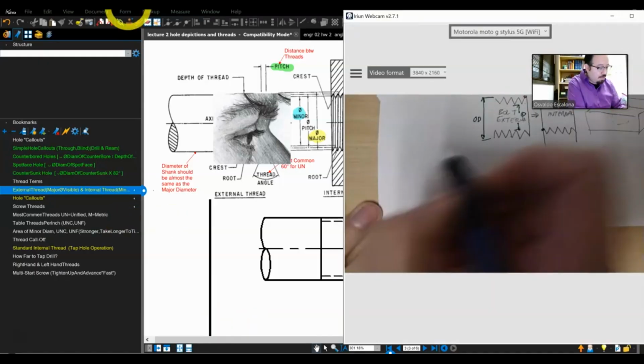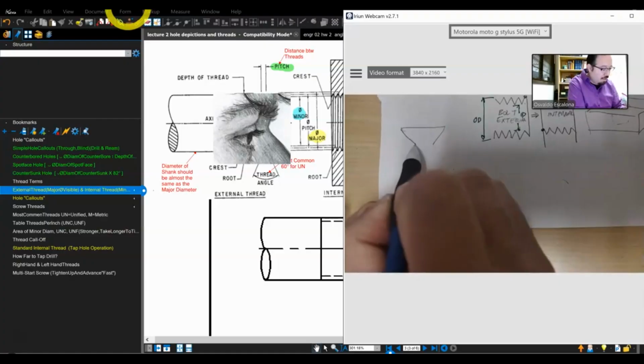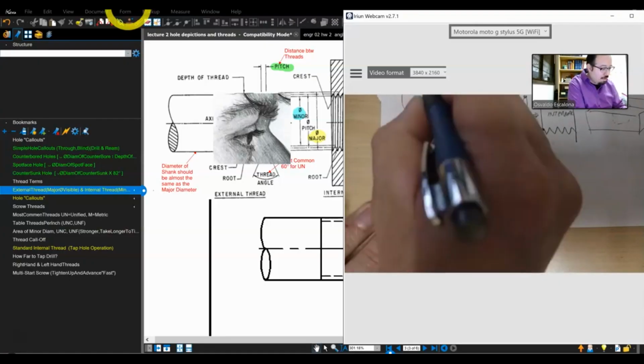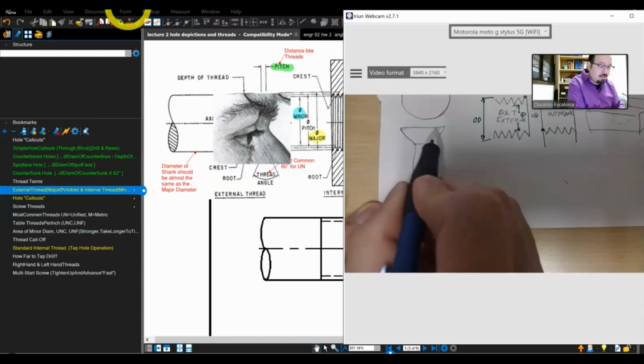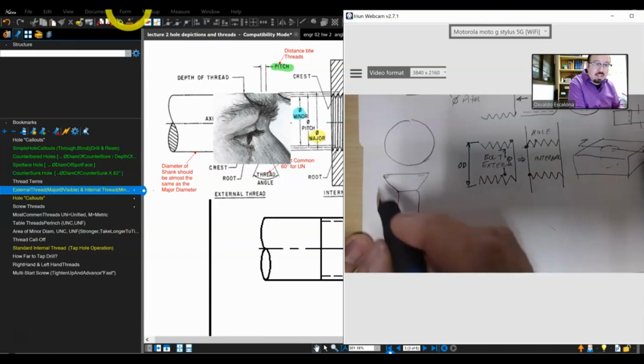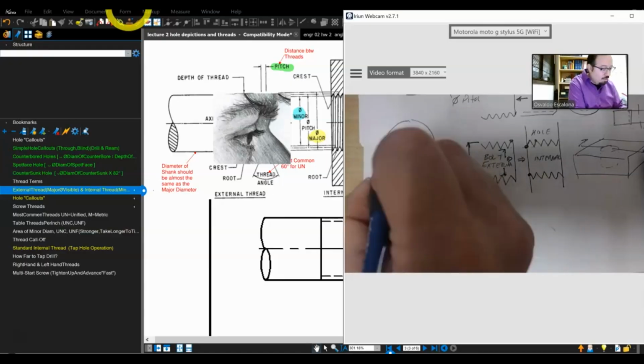Right? So let's say that the head looks like that. This is the bolt. So when you make the hole, you have to give it the diameter, and you have to call out the angle. The standard is 82. We usually draft it at 45.